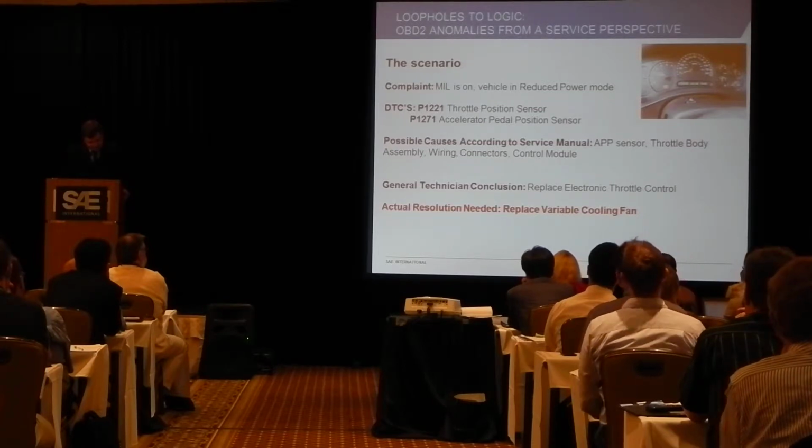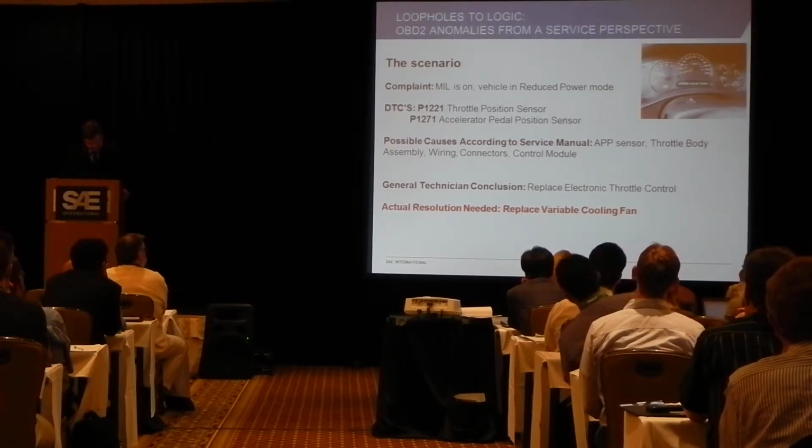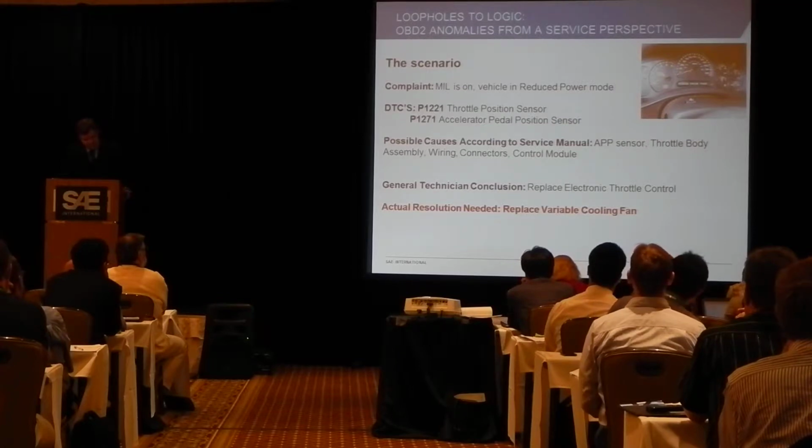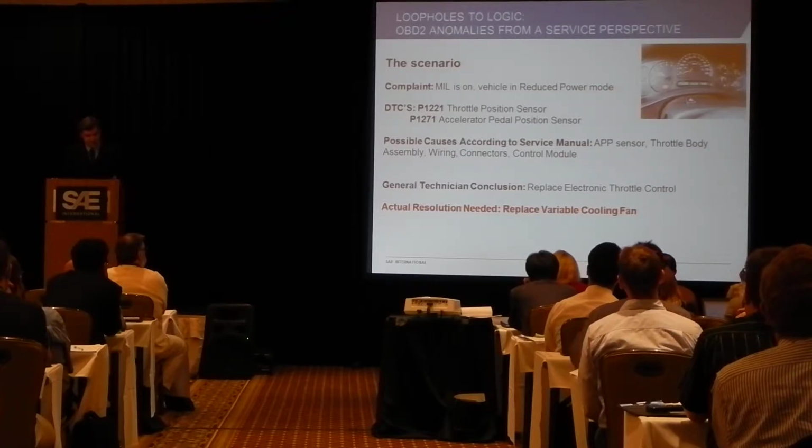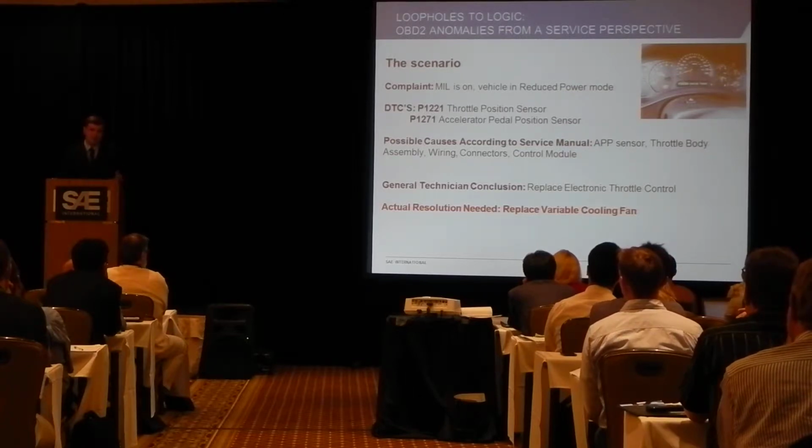Anyways, the DTCs, basically, the service information doesn't lead to the variable cooling fan. They do direct the technician to test your powers and grounds. Unfortunately, when you're testing your powers and grounds, you're in key on, engine off, because you've got to disconnect it, check it. Your fan's not going to be running, so you're going to have your powers and grounds.